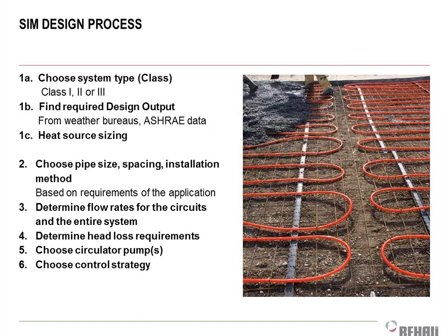Mike actually typed in a question asking, what's the average lifespan of a non-condensing boiler? If you look at the ASHRAE Handbook of Fundamentals, they give you lifespans for typical equipment. And I believe for non-condensing boilers, they give you 2 numbers in there, depending on what metal it's made out of, but the range is 25 to 35. I believe the cast iron ones are more towards that 30-35 range, and your steel boilers are more in that 25 to 30 range. So for non-condensing boilers, that's your answer there, Mike.